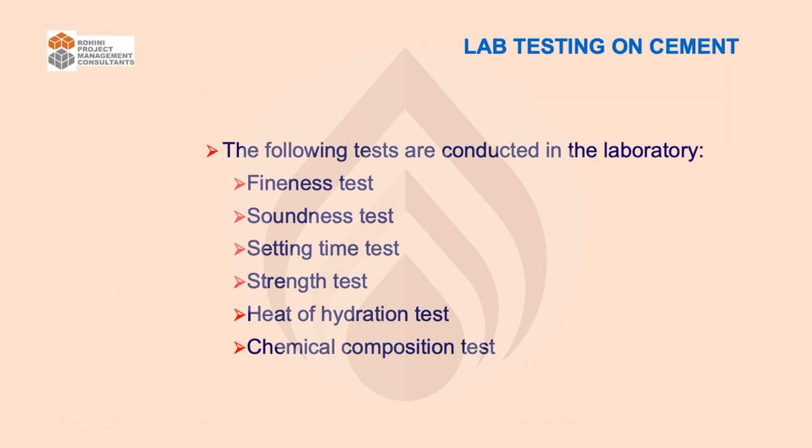Now coming on to the cement, right? For testing of cement, we are going for these tests. These are the lab tests which we conduct normally on cement. There are different types of cement. We'll not get into that detail. There is normal OPC grade, then you have a hydrophobic one, then, just for understanding, for railway there is a totally different grade of cement which is used for the sleeper. It is called a sleeper grade of cement. Then likewise, there are not less than 30 to 40 types of cement which can be used.